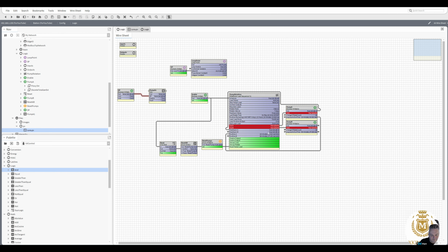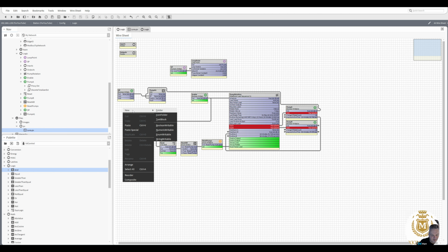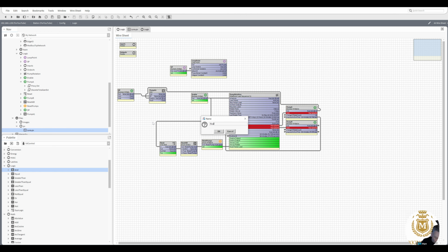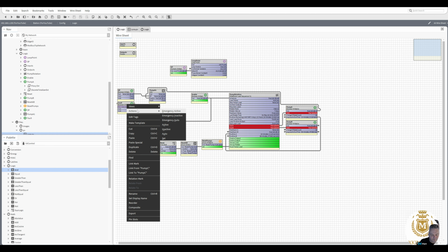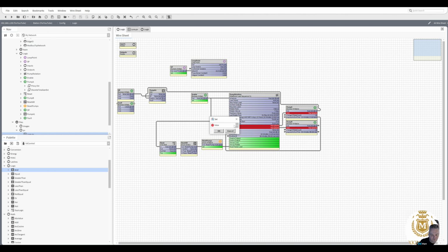The enable for pump A, I would naturally take that out and put that into the enable there, and then new Boolean writable, and this is a fault from the inverter or overload, doesn't matter what it is, and we always want that to be true. Let's just do set true.